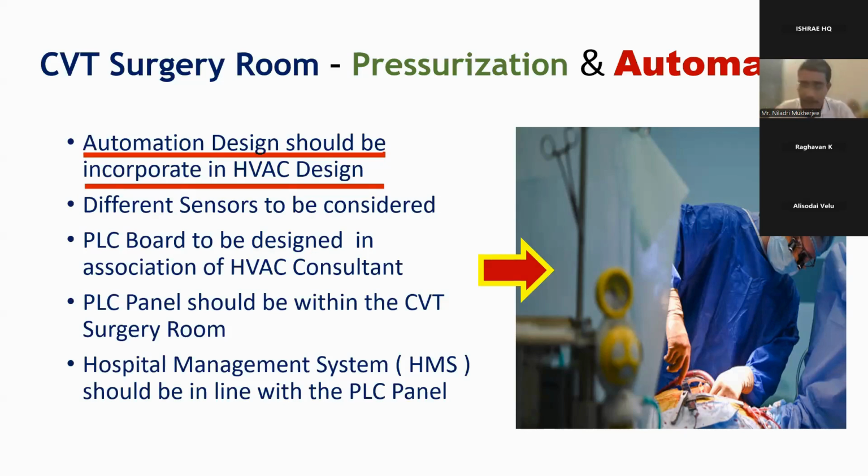Now, we don't want to disturb the main AHU with the AHU which is creating the airlocks. Because the return air which is coming goes to the same surgery room which is using an AHU. It has its exclusive return air duct. It will not mix up. That is why you don't want to mix up all the AHUs together.